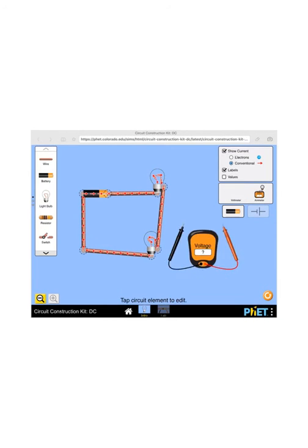If I measure the voltage across this battery, I'm still recording 1.5 volts. But if I measure the voltage across a light bulb, now I'm measuring 0.75 volts for the light bulb up at top and 0.75 volts for the light bulb down below. It's almost like that potential energy has been split between the two light bulbs in order to illuminate both of them at the same time.